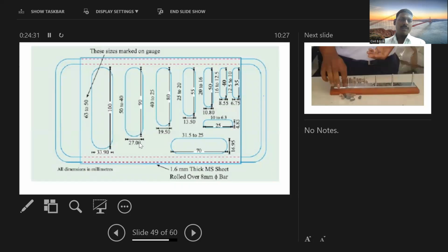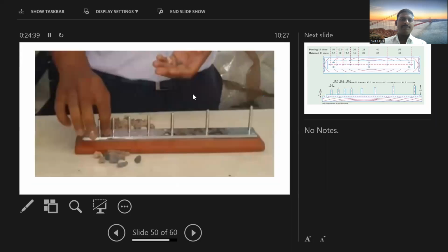So here again, if you see, the same sketch is there. Various sizes are given, and these sizes are in mm. So this is again elongation. How much elongation? How much is your aggregate's length? Thickness is another part, flaky is a different part, and elongation is a different part. So how much is it elongated? How long is it? It may be 20 mm thick, but elongation also affects the concrete workability.